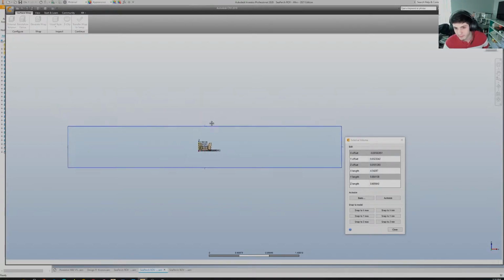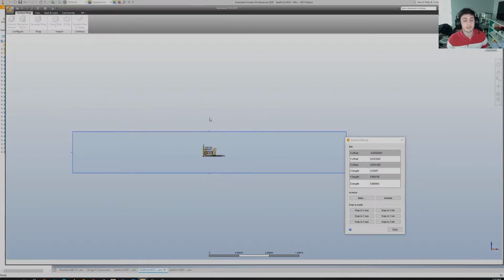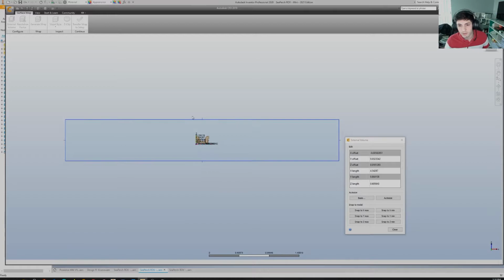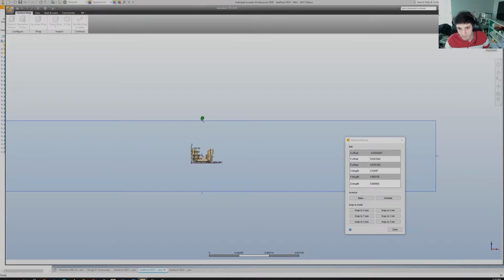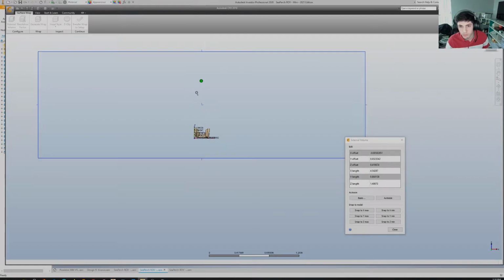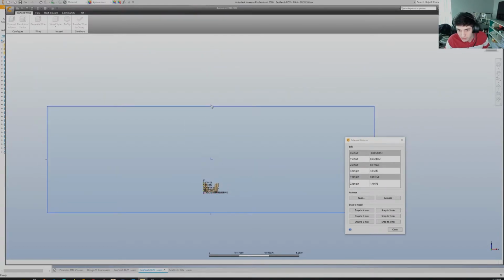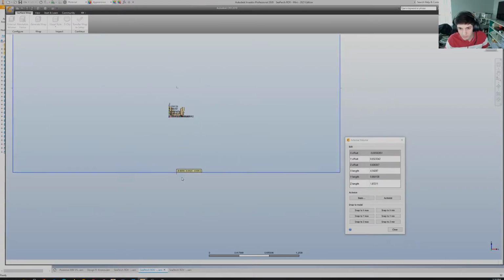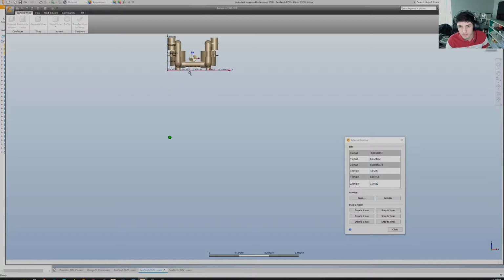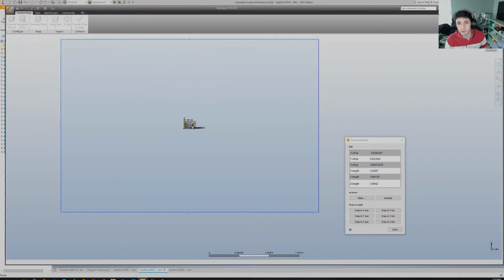Think of this like, let's say you have a submarine in the ocean versus a submarine in a large Olympic pool. When the submarine moves in the pool, the wake of the submarine is going to crash into the sides of the pool and alter the results. You need to focus on making sure that there's adequate space for the simulation to run in. So we're just going to make this fairly large, and you want this little cross to stay in the middle, so you know it's roughly equal on all sides.